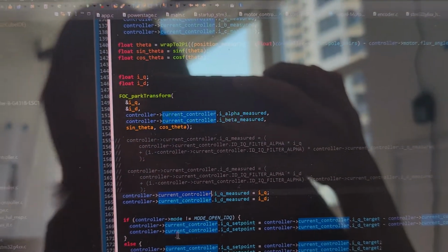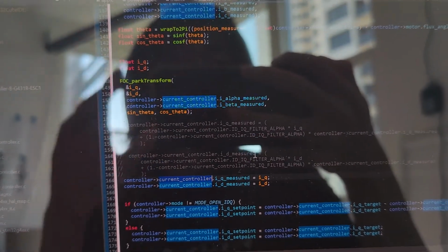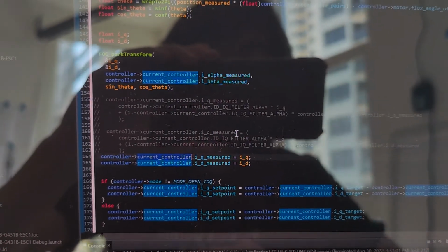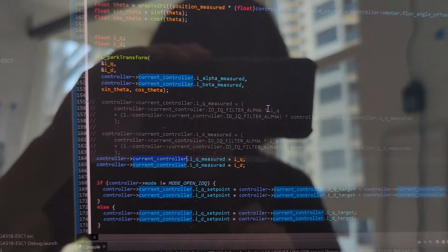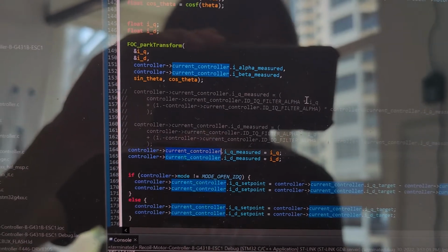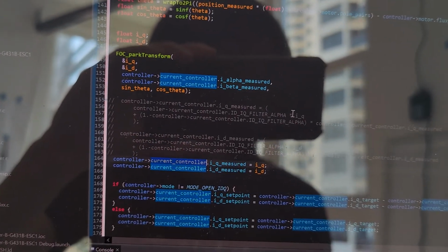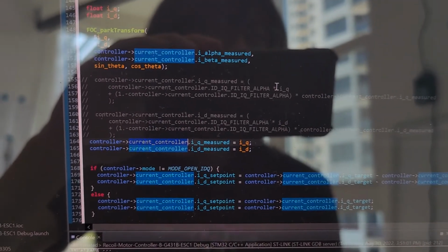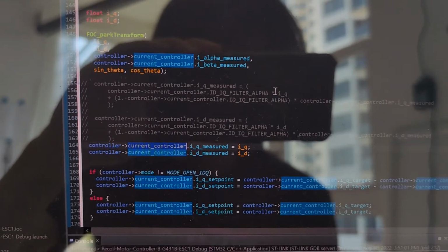So now I haven't fixed the code. The symptom was that I was able to configure the alpha to 1, and the motor runs kind of fine, not perfectly fine, but pretty fine. But any value other than 1, like 0.9, 0.8, like we're supposed to run at 0.1, I think. Some code even uses 0.05. Then it didn't work well.